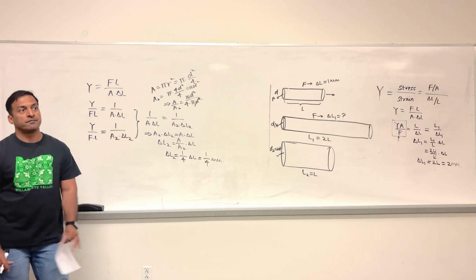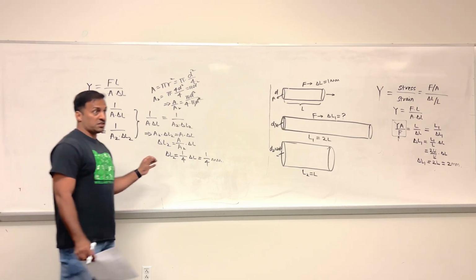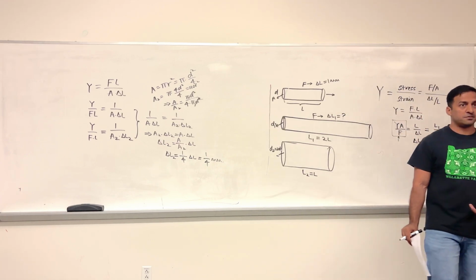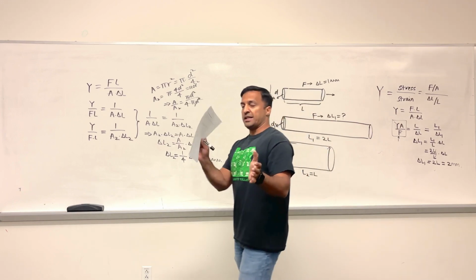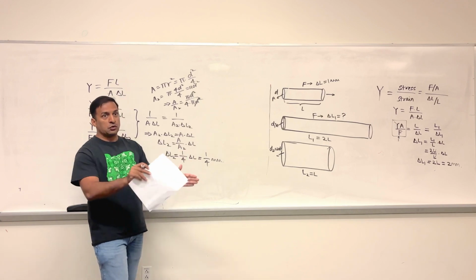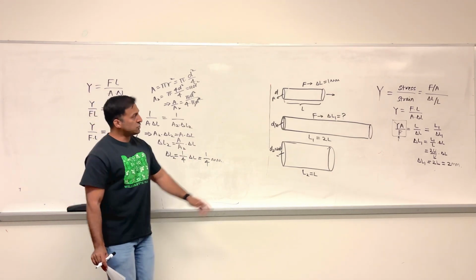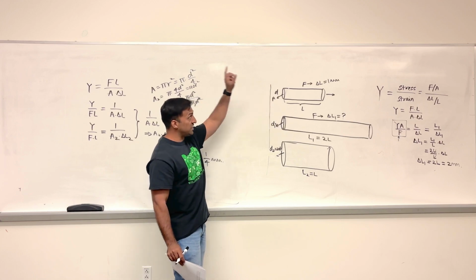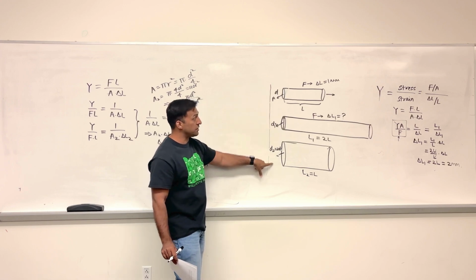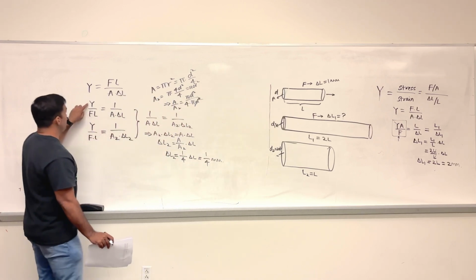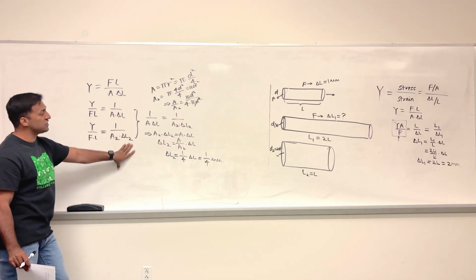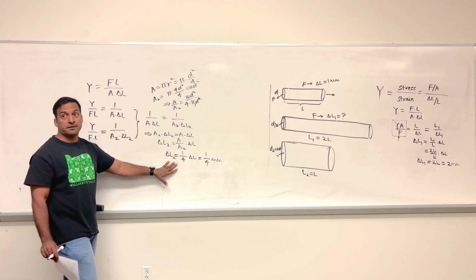So we have two results. Okay, just make sure that you understand how I solved it. And this is the general procedure in physics for solving any kind of problem. If it's a comparison kind of problem like this one, then you look for quantities which are not changing as you go from one situation to the next. So this was the original situation. Young's modulus was constant, force was constant, and length was constant if you go from first to the third configuration. Okay, so I separated out Young's modulus, force and length, and then exploited this to get this relationship, and finally I was able to find what I needed to find.